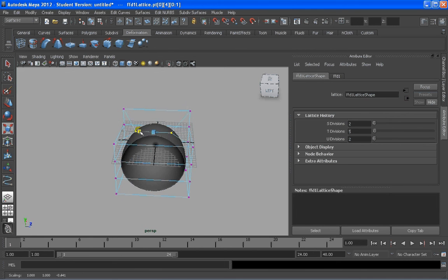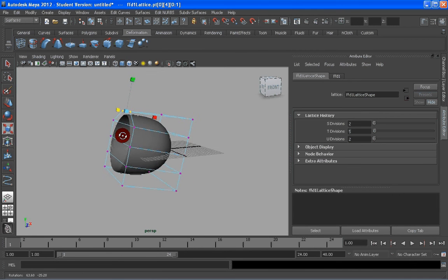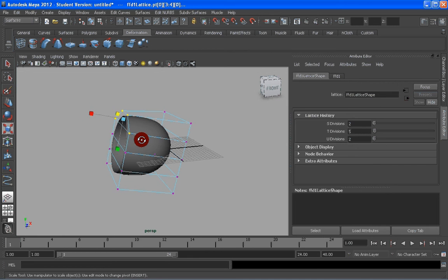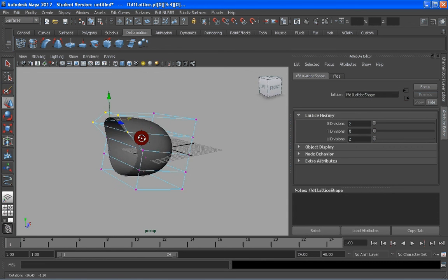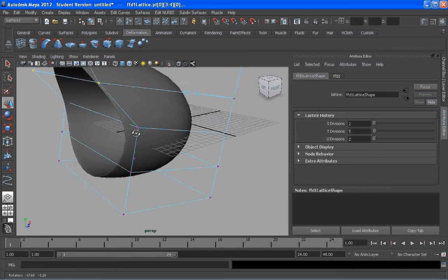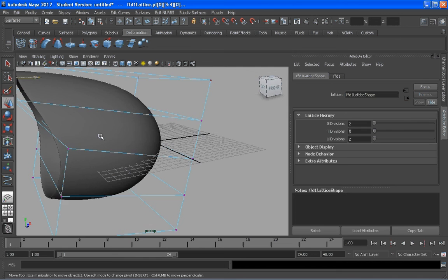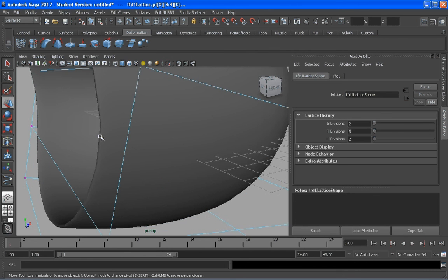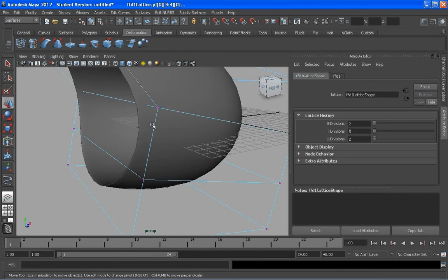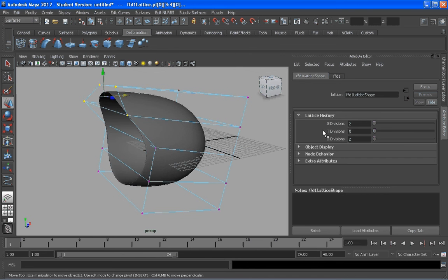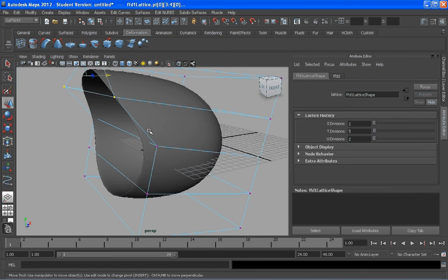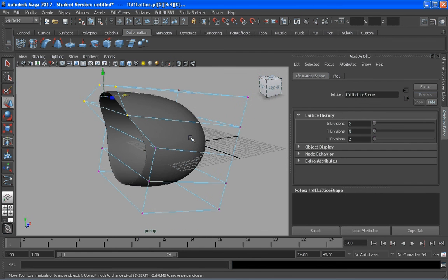So there's many deformations that you may end up with, for better or for worse, like this sample. But once again, the revolve has this characteristic that is kind of crumbly, so before deleting the history you should indeed change the span number, so you're working with a good number of geometry, so when you render it, it looks perfect. No? Okay, I think it's a great tip and hint right there.